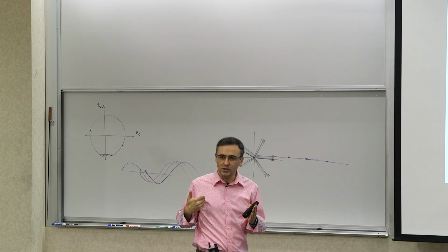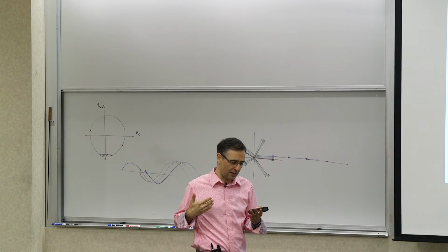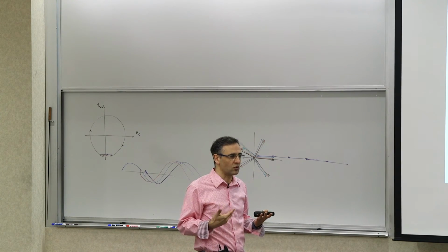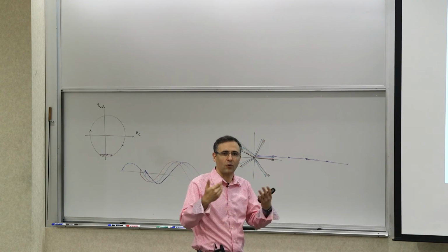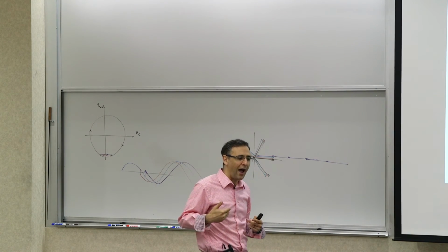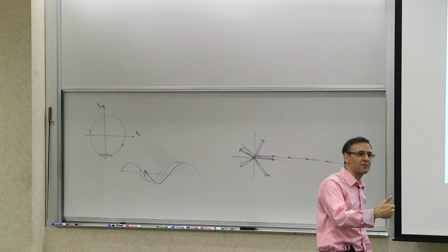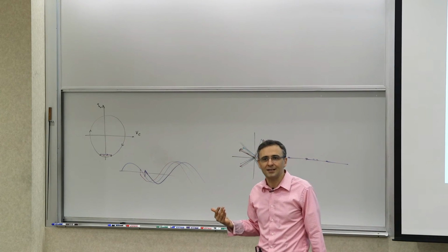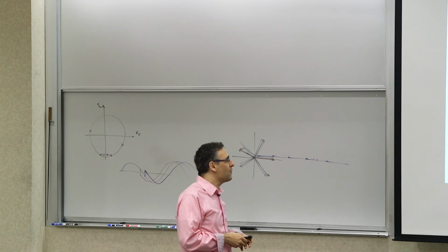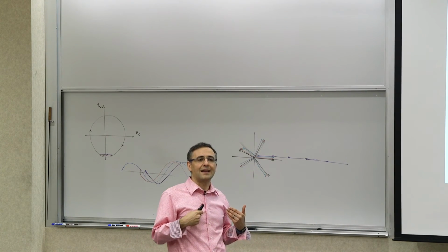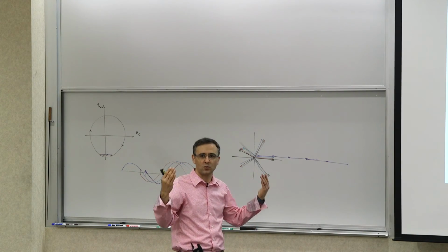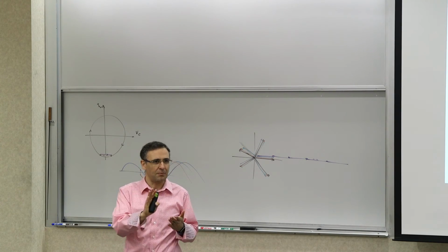Now, do you expect the noise of this first stage and second stage to be correlated? If they're not related to each other, if they're intrinsic noise sources, like a white noise source generating that, these will be uncorrelated, right? So how do you expect these random timing jitters that are not correlated with each other to add? You expect them to add in power, right? So the variance will grow linearly. Sigma squared would grow linearly because you're adding in power.